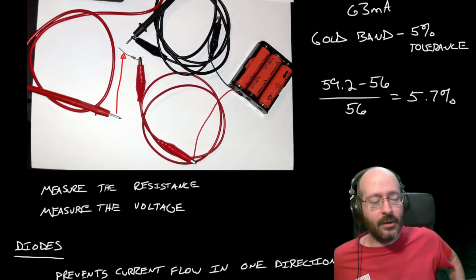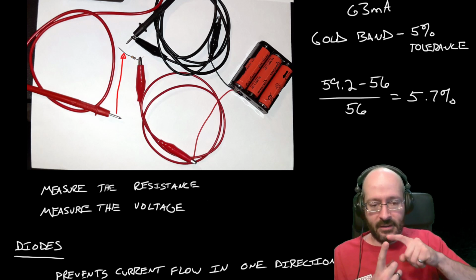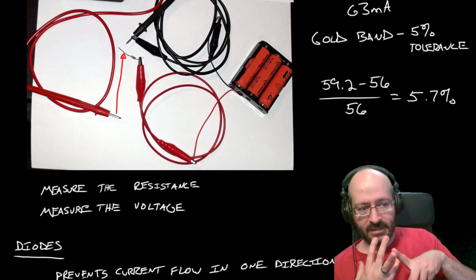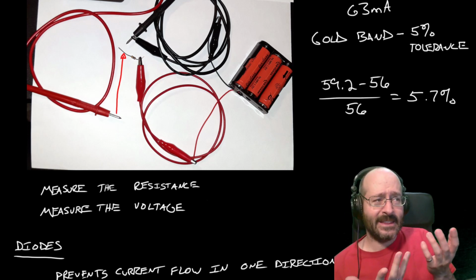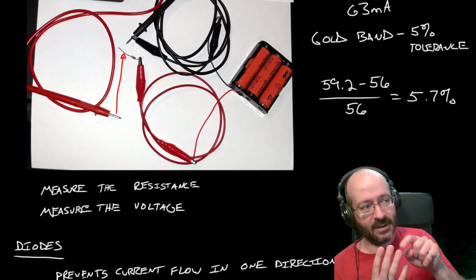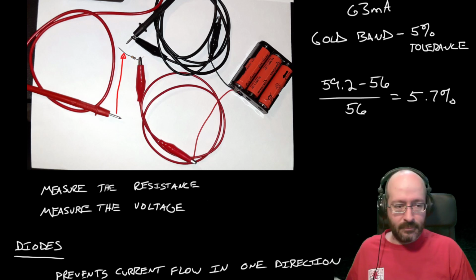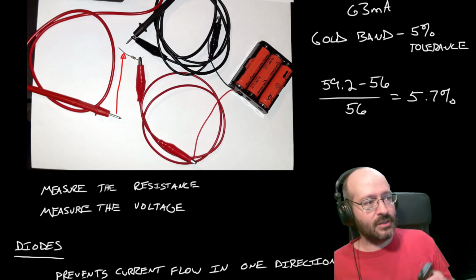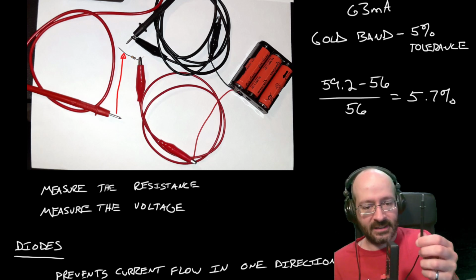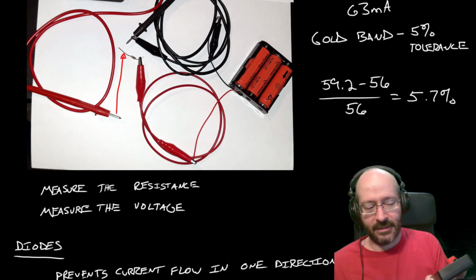56.3. Wow. Okay. So there's some error in one of these measurements. We took 3 measurements to make this happen, right? We measured voltage, we measured current, and we measured resistance. And they should follow Ohm's law, and they closely do, but not perfectly. So one of those 3 measurements has error, and it's not unheard of. Wire isn't without resistance. So even the probes that you're connecting to the circuit have a little bit of resistance. Measuring something always changes the value, right?